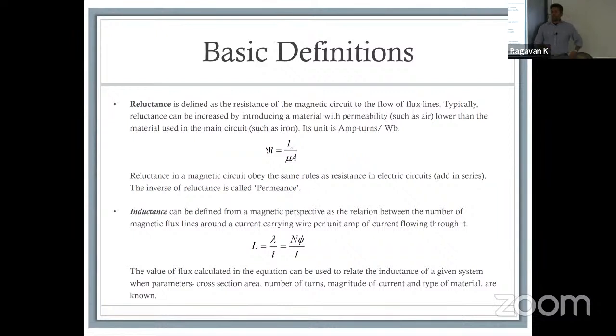If you implement methods like vector control or field-oriented control, you will remember that we actually talk about concepts like ID, IQ, LD, LQ, right? We are talking about direct and quadrature. What we're trying to do is make the AC machine look and behave like a DC machine. We are trying to decouple the component that creates back EMF and the component that creates torque. We're trying to separate them and make it look and behave like a DC machine. So torque and back EMF are unconnected. But for getting there, you need to know this fundamental.